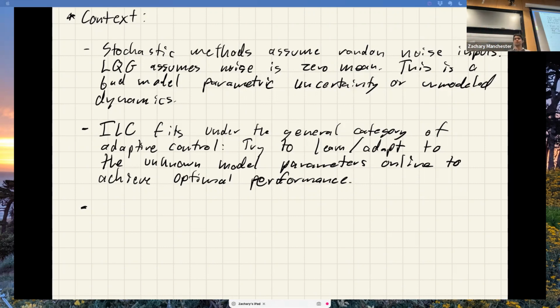Say I have 10 robots and there's 10% variation due to manufacturing weirdnesses. Or I have a quadrotor and I know there are going to be wind gusts, but I can bound how big they're going to be. You're not going to try to figure out those parameters or estimate the wind online. You're going to design a feedback controller offline that says, given these bounds, I guarantee this one controller will work across that whole range of robots and parameters and give me reasonable performance, right? That's the big picture idea: design once, don't adapt, but be super conservative.